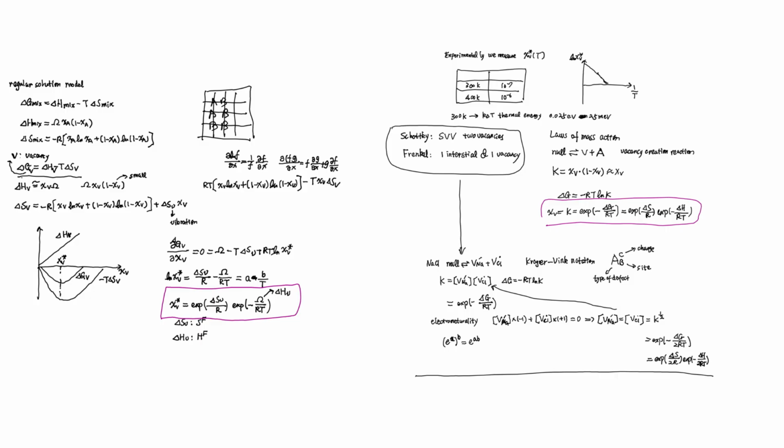Again, why are we saying that? Because if you remove a certain amount of A and create a certain amount of vacancy, it reaches the equilibrium state, because the energy penalty and energy gain are balanced, which means the vacancy and the rest of the A atoms are forming a chemical equilibrium. So we're going to write down that chemical equilibrium, and for a chemical reaction in equilibrium, we can